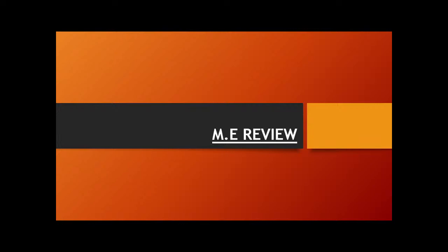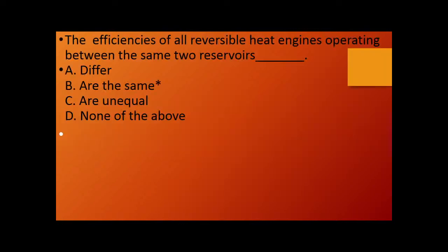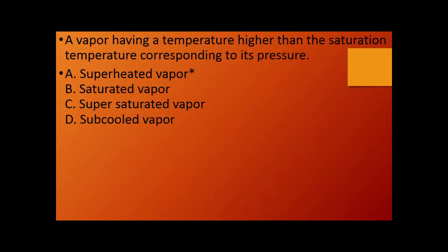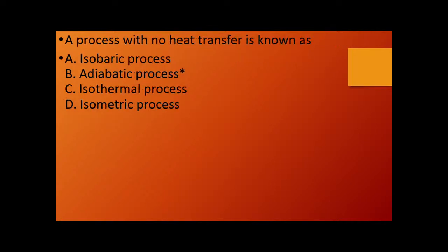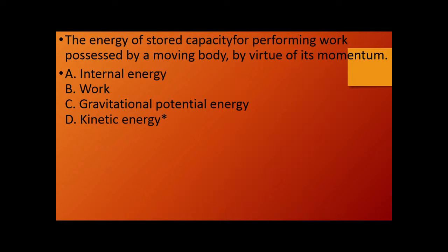So, mechanical engineering review. The efficiency of all reversible heat engines operating between the same two reservoirs are the same. A vapor having a temperature higher than the saturation temperature corresponding to its pressure: answer, superheated vapor. A process with no heat transfer is known as adiabatic process.